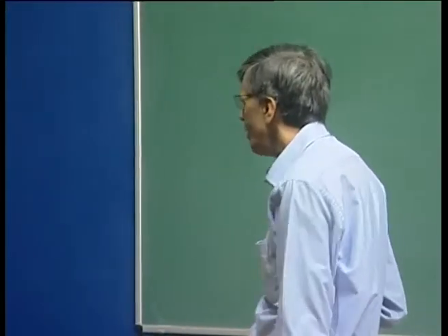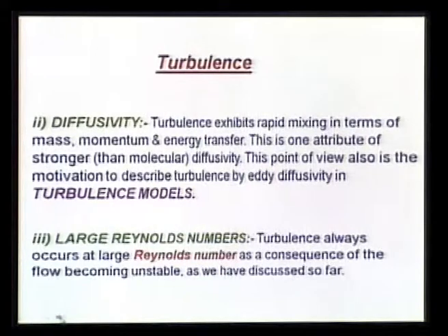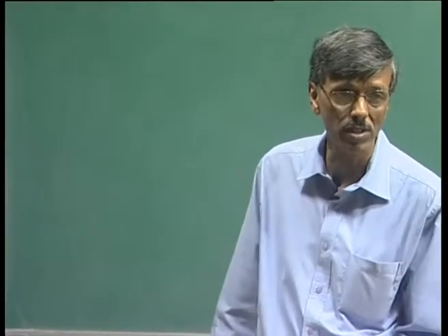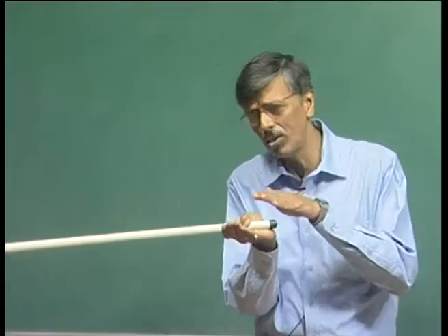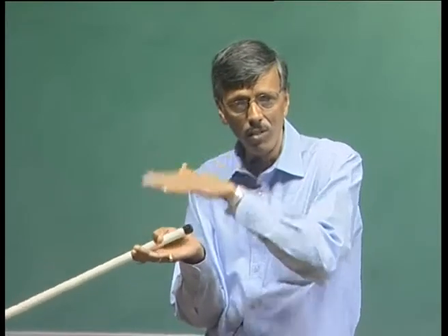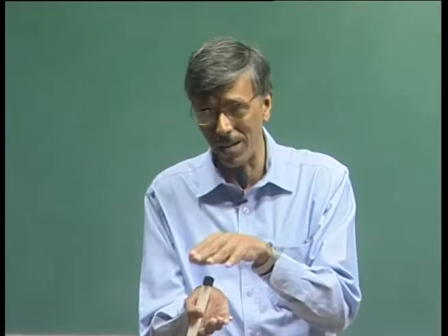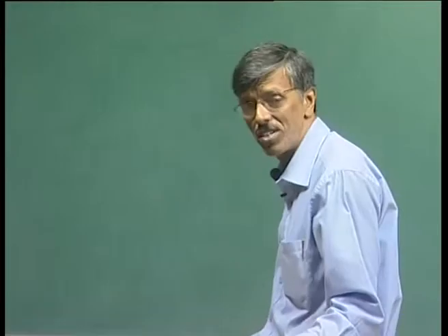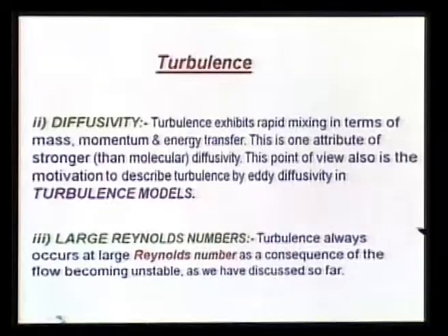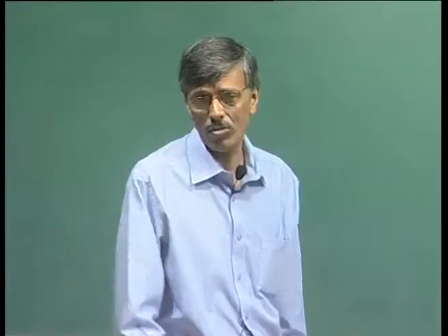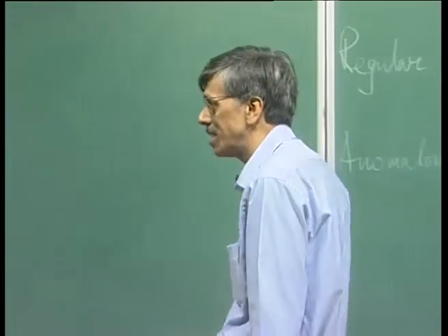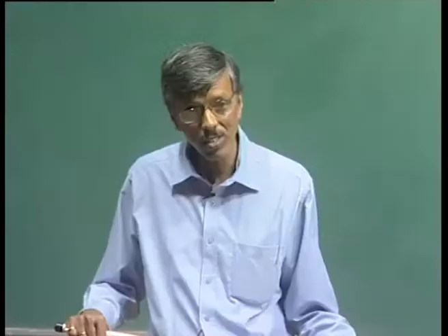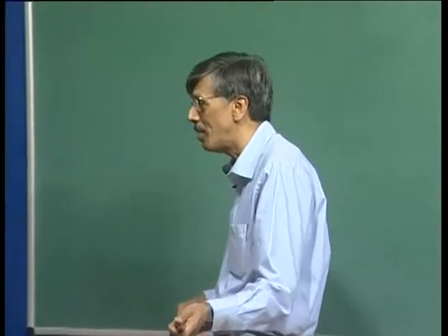Okay. What you need to understand is that if you did not have the turbulence, then the boundary layer, the shear layer would have grown, and that mechanism was given by kinematic viscosity, the molecular viscosity. So, molecular viscosity is like one layer of fluid going over the other, and then they are transferring momentum in an orderly fashion from one to the other in a macroscopic sense. But in a microscopic sense, you can think of those molecules or the constituent particles exhibiting rapid variation, but in a macroscopic sense they are still very regular. However, when you have turbulent flow, even at the macroscopic level, you are going to see a massive increase in diffusivity. So, if I try to characterize my turbulent flow in terms of a diffusivity coefficient, that coefficient of diffusion has to be significantly higher than what you get in laminar flows.